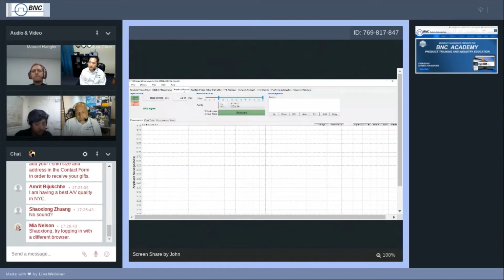Next tab is the amplitude noise. This is very similar to the absolute phase noise, except that this measures the variation of the amplitude. Next is the high drift absolute phase noise tab. This again looks very similar to the absolute phase noise, except it's more focused on a drifty source or oscillator, like the YIG, DRO, and SAW, to name a few.